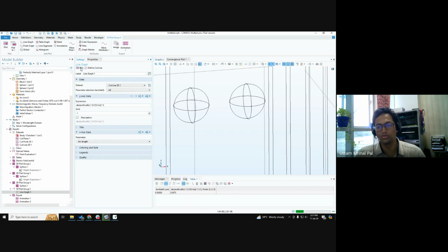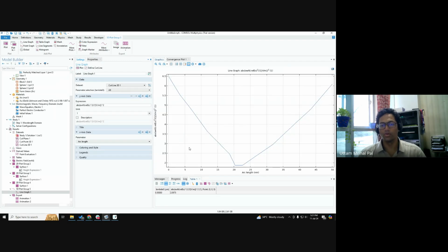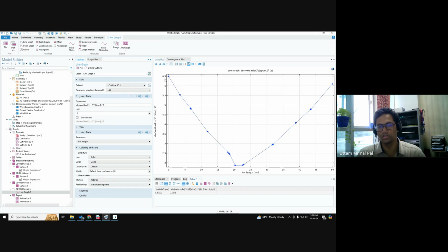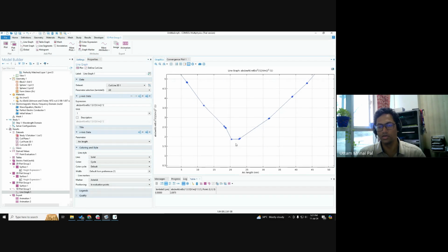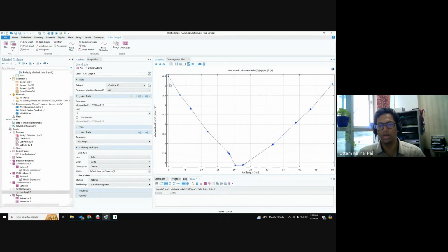And here you should be able to see how this enhancement factor is going from here to here. Okay, again, it is always good to put an asterisk line marker at evaluate point, so that it is based on the mesh. You can see that the enhancement in the center is almost around 1.92, but at the edges it's very high.